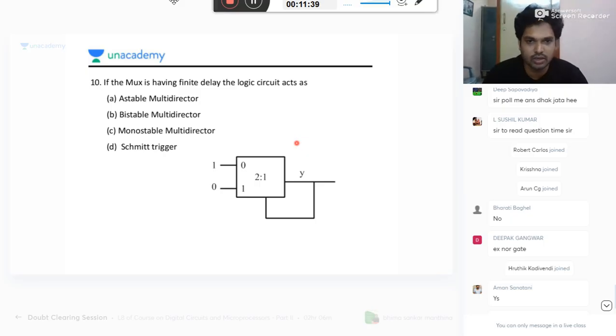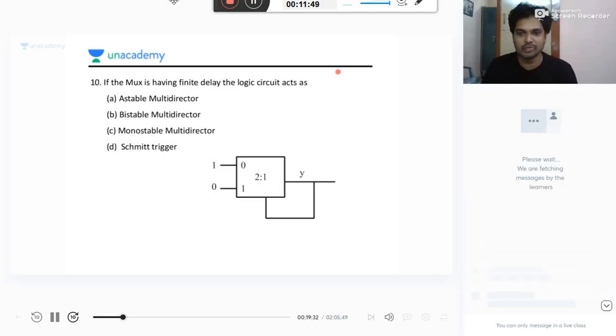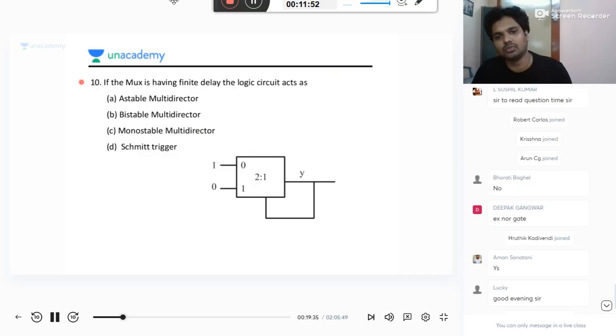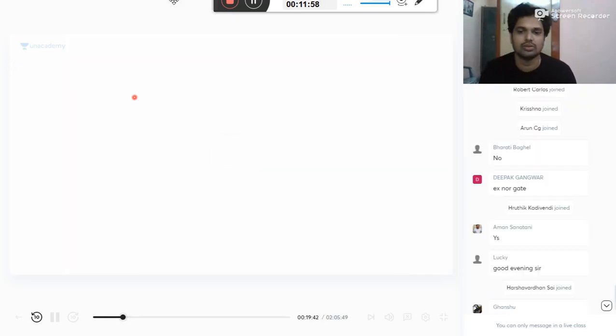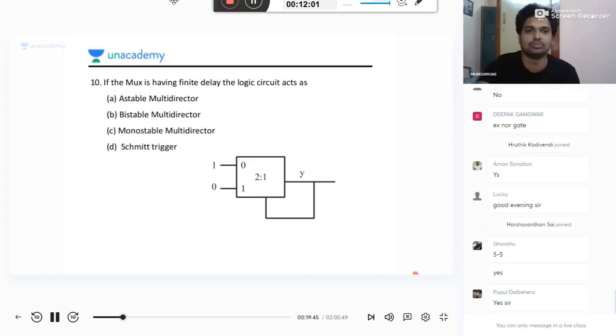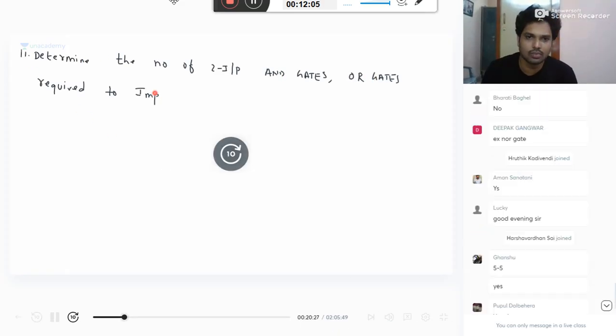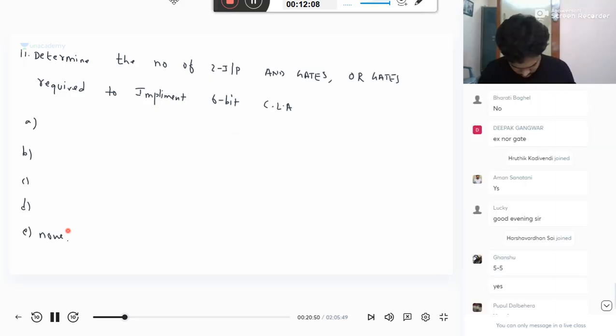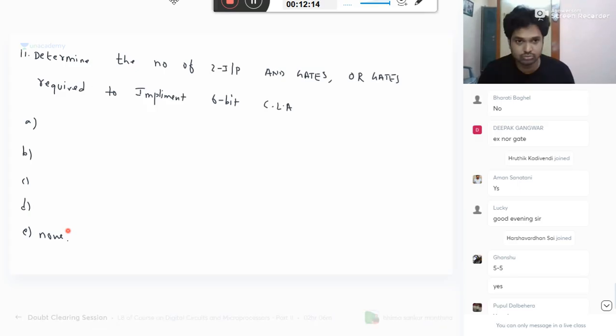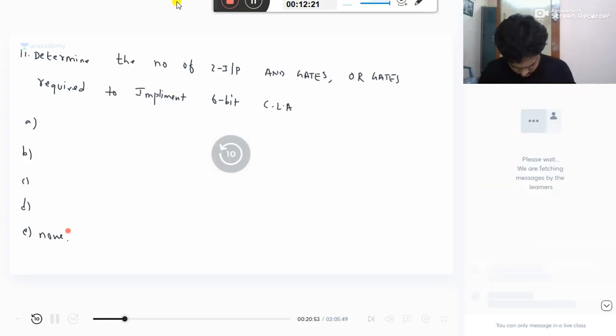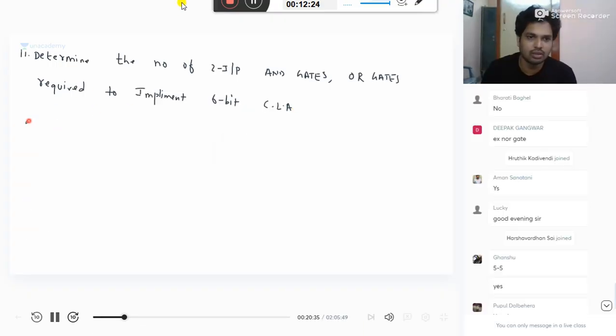For SR flip flop, there is no race condition. Race condition will be occurring for whom? That is for JK. Invalid conditions will occur here. Race around condition will occur for JK flip flop. Don't tempt with 1-1. That is tomorrow's topic. Listen here. Any problem, Rahul? What do you mean by race condition? Output toggles multiple times in the single clock. Okay, it will not occur in D flip flop. How will it occur? D flip flop is having only one input.